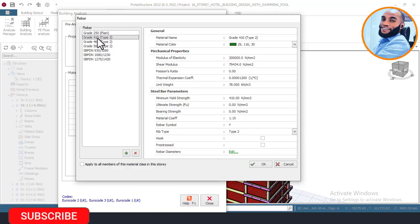But for me, I always choose 410, except I have a very good confidence that the company that I'm buying the steel from has a good reputation. I can now go and do that. Okay, but I would advise you just pick 410 for safety purposes. Okay, so right now I'll come here and then click on apply to all members again. Now before I say okay, I will have to edit my rebars.